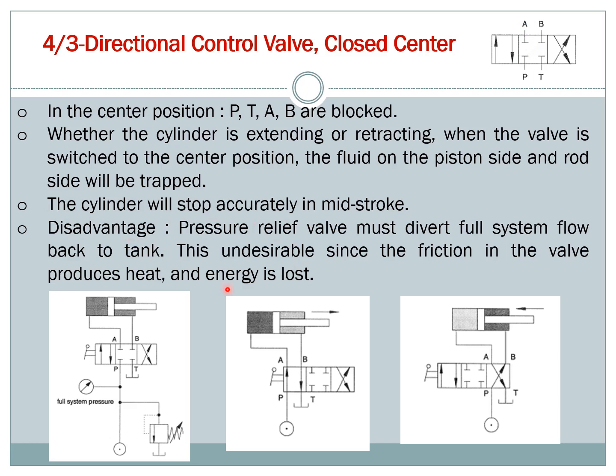Okay, so the disadvantage of a closed center direction control valve is that the pressure relief valve must divert full system flow back to tank. So when it's in the center position, the oil from all these ports, A, B and pressure, must be channeled back to tank. So this is undesirable.